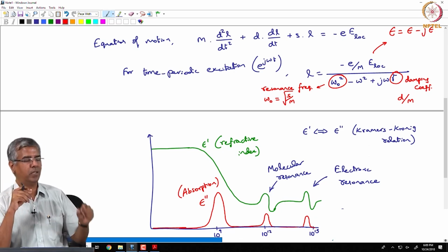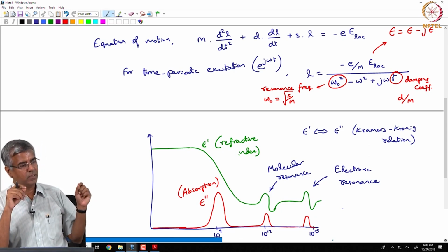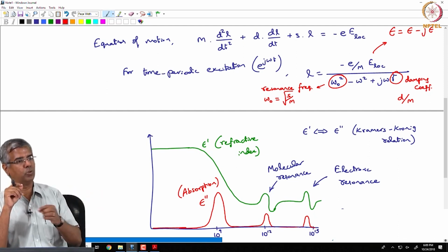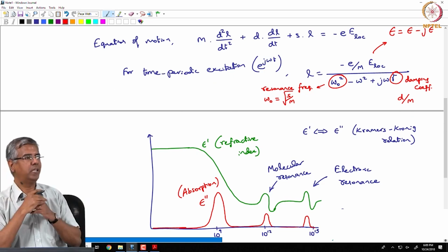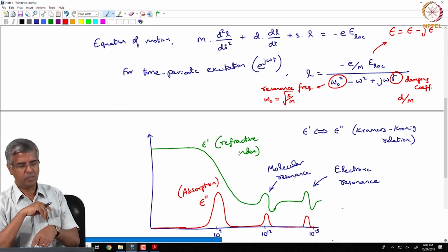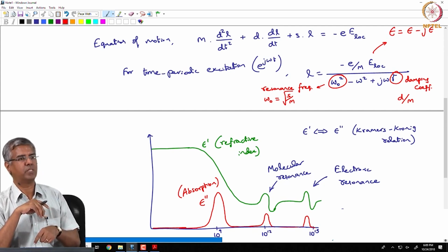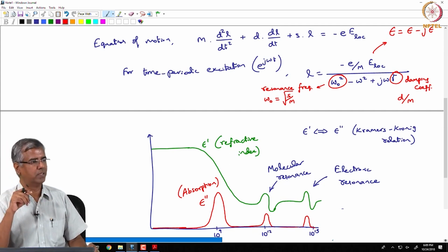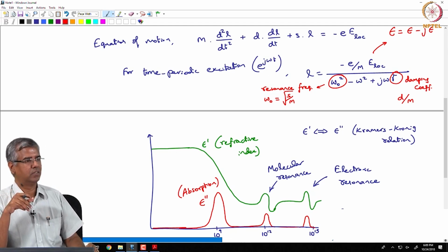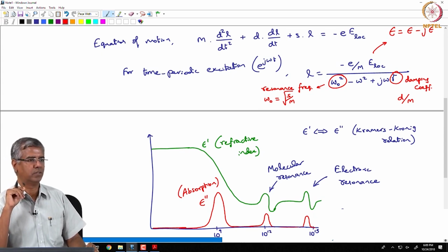In a coaxial cable, your field is confined between the two conductors. So, the field is actually propagating through that dielectric material between the two conductors. That dielectric material is similar to this, it is not able to respond to high frequency excitation in the order of gigahertz. Okay. So, you have that loss that comes about.